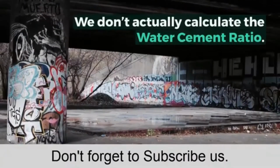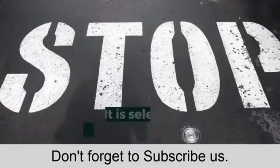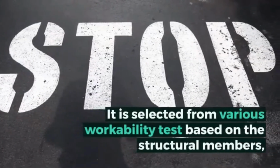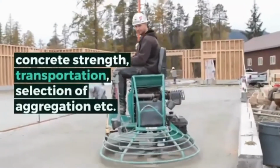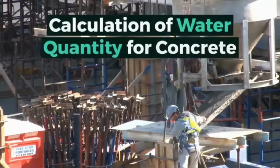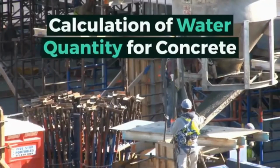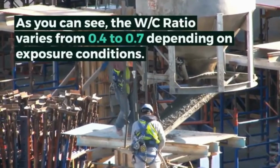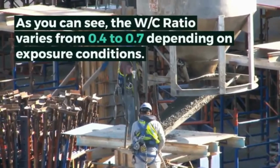We don't actually calculate the water-cement ratio. It is selected from various workability tests based on the structural members, concrete strength, transportation, and selection of aggregate, etc. Calculation of water quantity for concrete. As you can see, the water-cement ratio varies from 0.4 to 0.7, depending on the exposure conditions.